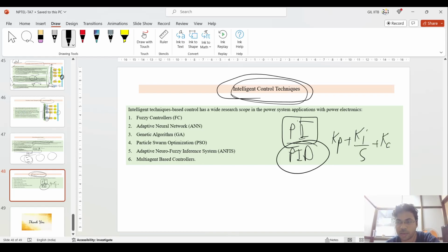Okay, this is the kind of system. And you have to put certain KP, KI, KD values. So suppose I'm generating this reference, taking ID star minus ID, where ID is the actual. This is the reference that you have to minimize.